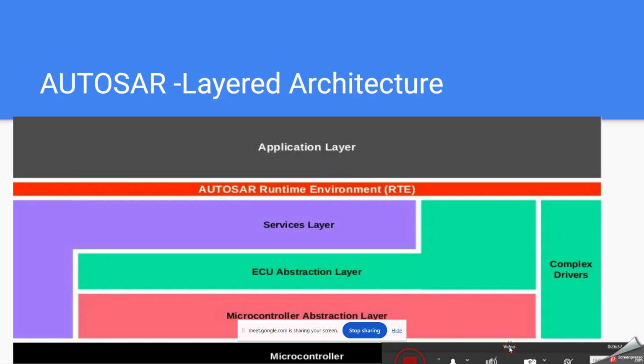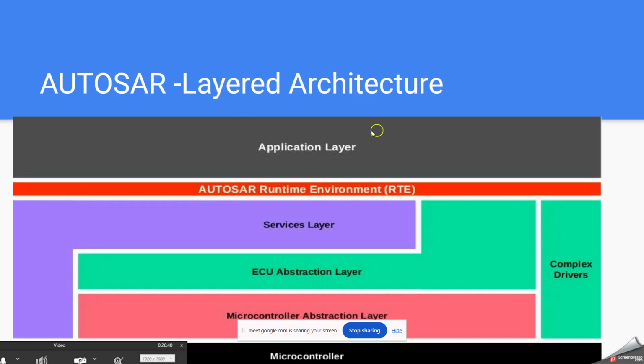Additionally, whatever flow we are doing, it is coming from application, RTE, service, ECU abstraction, all the layers, and you may feel like this is time consuming. Autosar does support the complex driver design also. There you just write your own software component, you create, let's say, CDD underscore your own application, you connect the ports to RTE, and directly from the complex driver you can reach the microcontroller. Let's say you want to read some PMIC pin, to check some over voltage or under voltage, or something airbag related, then you don't have that much time to react.